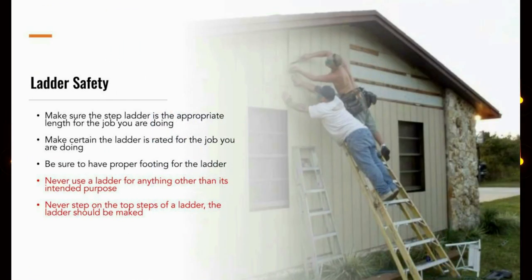Here in this picture, 2 guys on the same ladder. Absolutely terrible idea. I guarantee you they are way overweight on the ladder. It's sitting at the wrong angle too. Ladder safety, make sure the step ladder is the appropriate length for the job you are doing. Make certain the ladder is rated for the job you are doing, and that's in terms of weight rating. Be sure to have proper footing for the ladder. That's those nice rubber feet on the bottom or the claw grip feet.